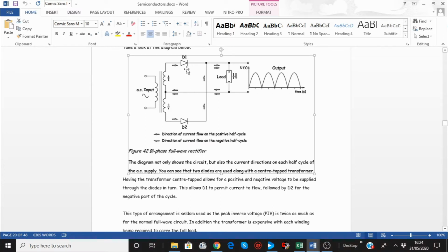Obviously you could put the diodes facing backward, and then you'll get bumps at the bottom if you wanted to, but you just learn one way or the other. So this circuit basically turns full AC into full DC, full wave rectification, but it's still a varying DC. It's a DC, but it's not a very good DC.